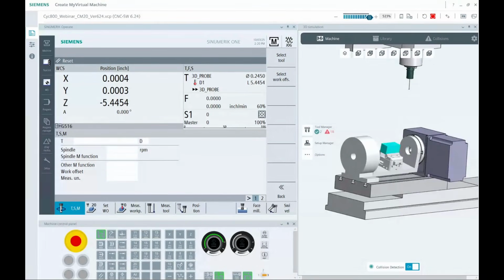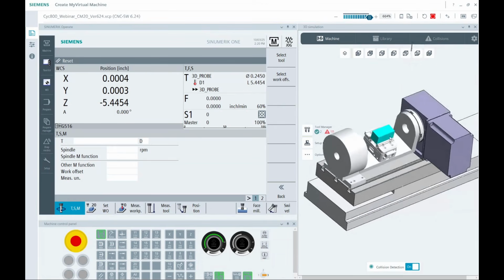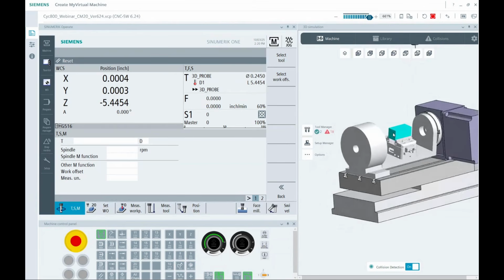And there's always most likely going to be something. It's very difficult for me to bolt this stuff together and have to align it mechanically so it's not spun, and that's okay. But I do need to make sure that I align this surface, this top edge. Let's say I'm going to work from that top edge before I set my part 0.